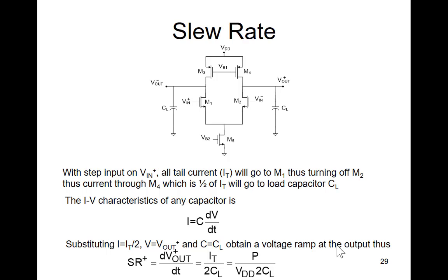Yes? So if I'm in the lab and I'm trying to characterize an op amp, in the lab we would probably want to use a square wave since we want to be able to observe the periodicity on the oscilloscope. If I'm not changing which input I put my square wave on, from the inverting input to the non-inverting input, am I not truly capturing the rising and falling slew rates? Yes. If I understand you correctly, you put a big positive going step and negative going step on the inputs. You'll see an output that slews down, saturates, slews up, saturates, slews down, saturates, and so forth. So you will get both positive and negative going slew rates on one display on the scope. The one edge will be the positive slew rate, the other edge will be the negative slew rate.